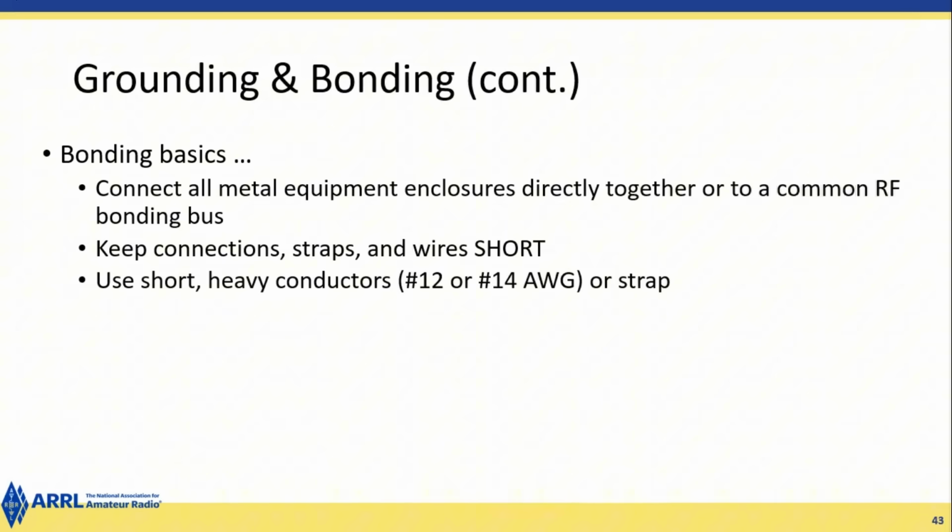You sort of have to play with them based on what your RFI interference is. Ferrite beads placed on cables to prevent RF common mode from flowing on the outside of the cable or shields is another way to try to suppress RFI. Interference to audio equipment and sensor connections can be limited by using small capacitors, 100 pico to nanofarad size, across balanced connections.